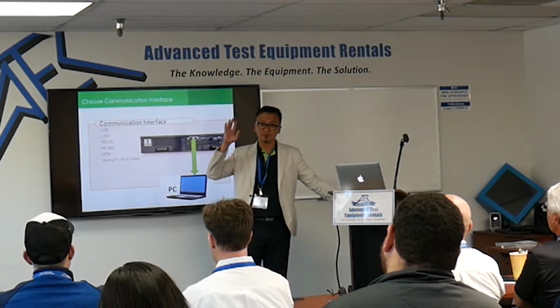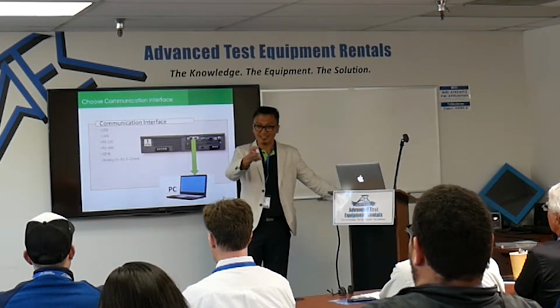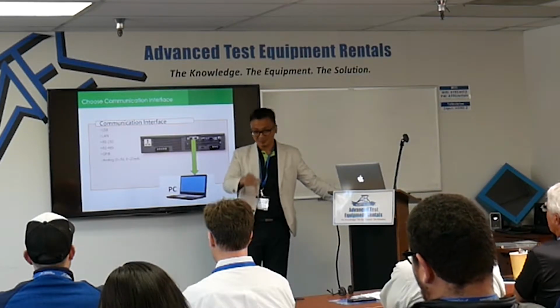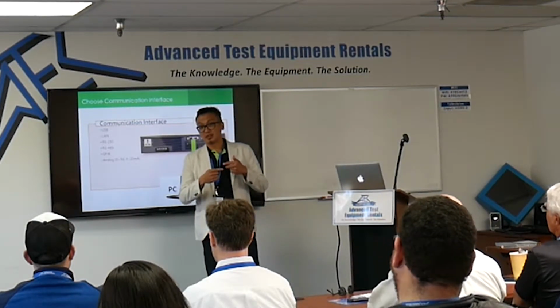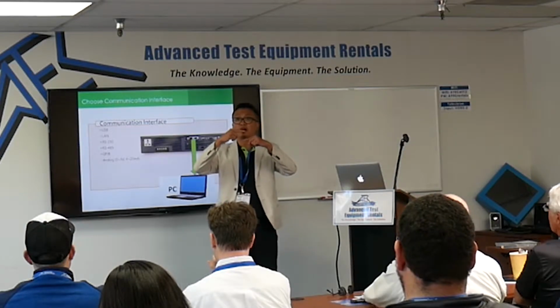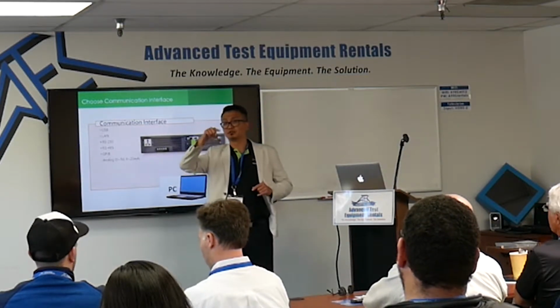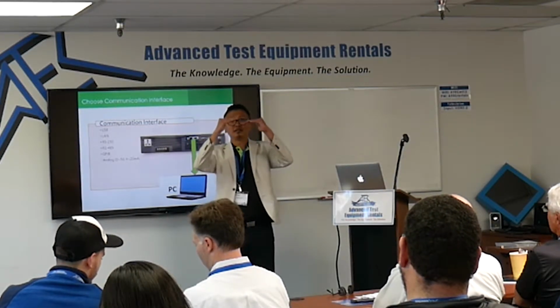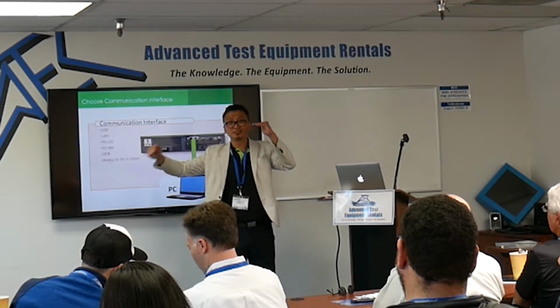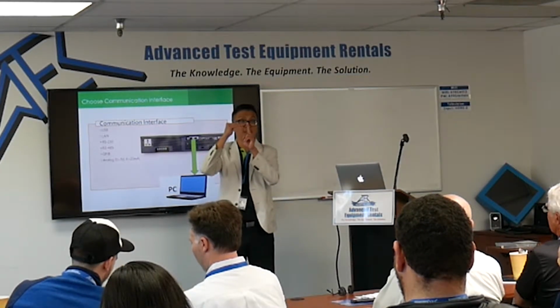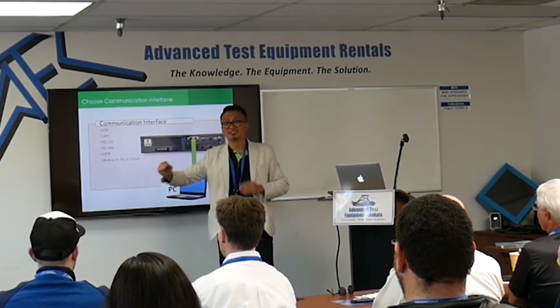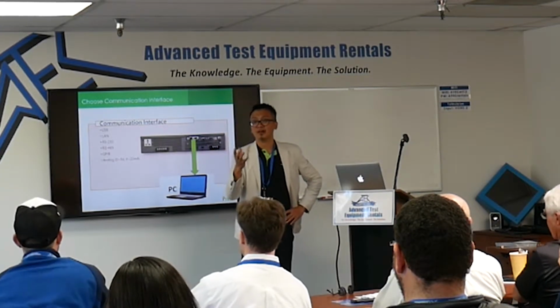The reason, does anyone know the reason? Right, because RS-485 is differential. RS-232, I'm not sure if you're familiar with the 232 signal. If your distance is long, the voltage will drop, the signal will drop. So for long distance, you may get a lost message.